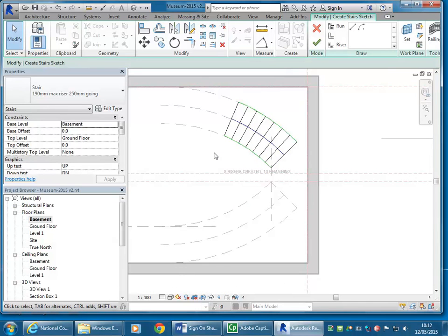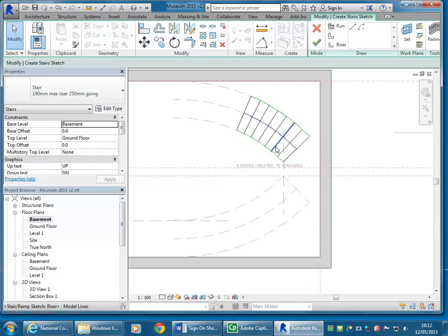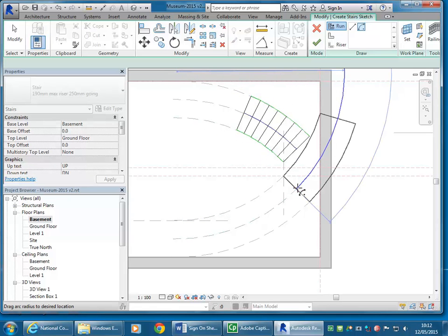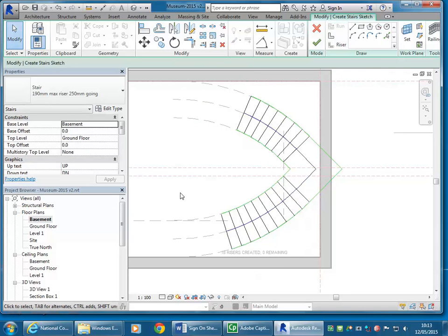So SC is a really good option you can use to snap to the centre of a curve. I'll show you in a minute though, if you want to mark that centre point, there's another way of doing that. But now I'm just going to go back to the Run tool, change it to drawing a curve again, and then again use SC to snap to the centre of this curve, which again is up here. And now I can begin it on the landing and just take that around to finish it.